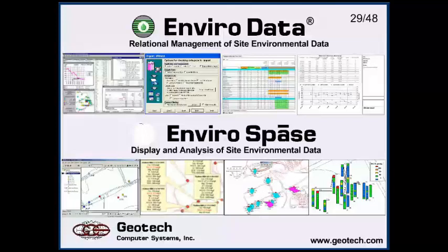It's also used in environmental work because if you really know what you're doing, you can use the output of the cone penetrometer to get a general idea of what the transmissivity of the materials are. So for example, if you've already done a soil boring and you know you've got 20 feet of clay and then 10 feet of mixed sands and silts and clays, then as you're driving through that material, it'll go faster generally through the porous zones. And so by looking at where they are and how thick and how many there are, that can give you an idea of what the hydrogeologic regime is down there.